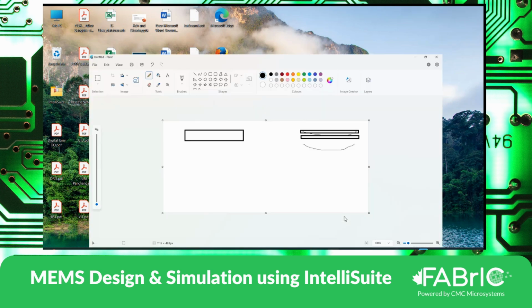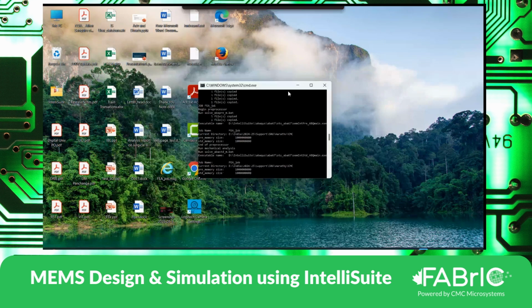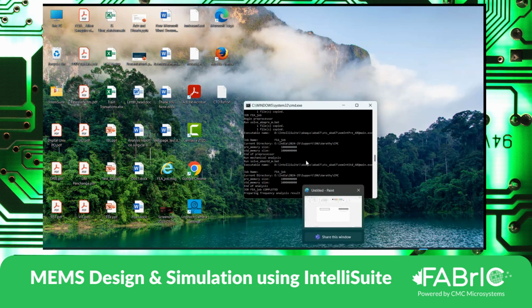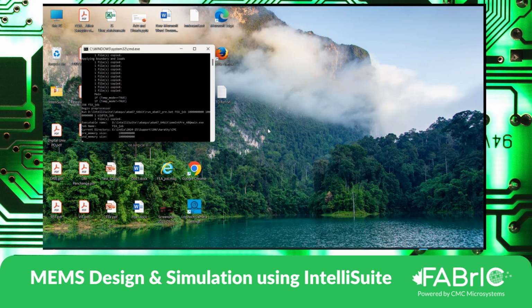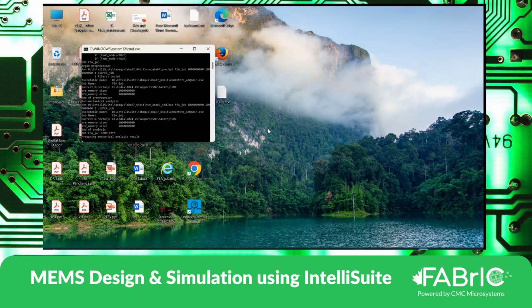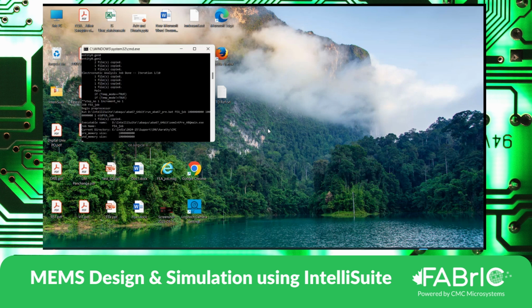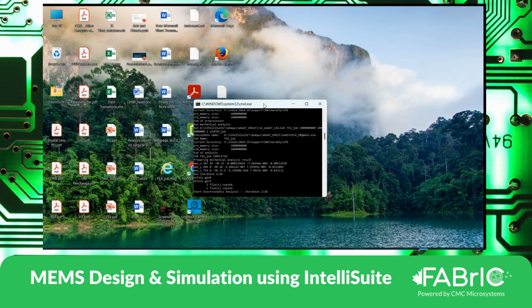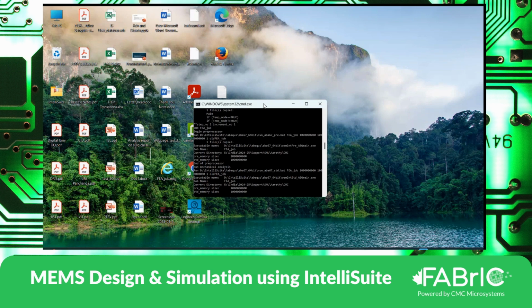And it automatically modifies the mesh in narrower regions. Exactly. You can also choose, for example in a comb drive, to refine the mesh around the comb drive fingers, and the rest of the structure can have a much wider and broader mesh for easy computation. That's right. Thank you.